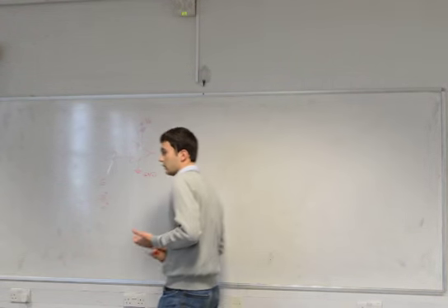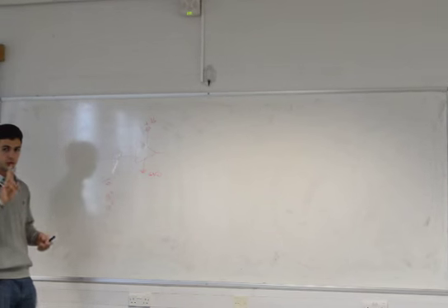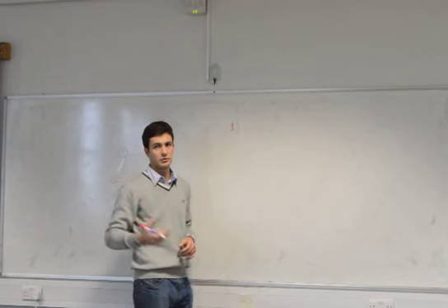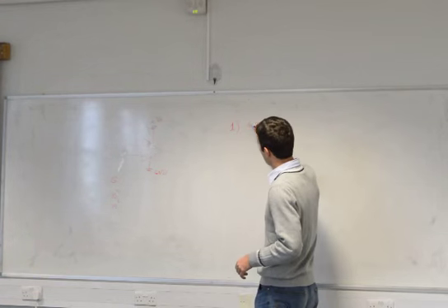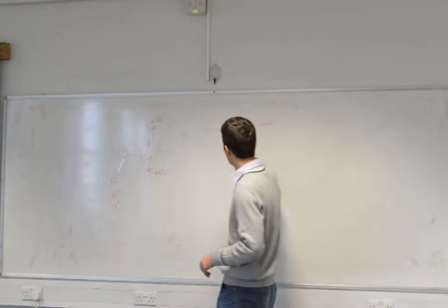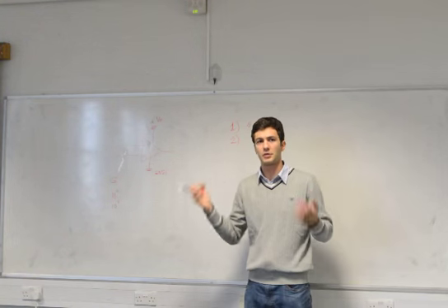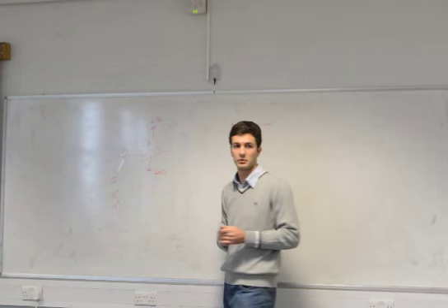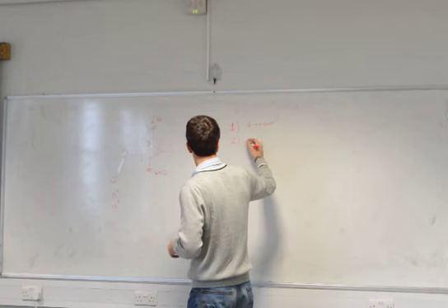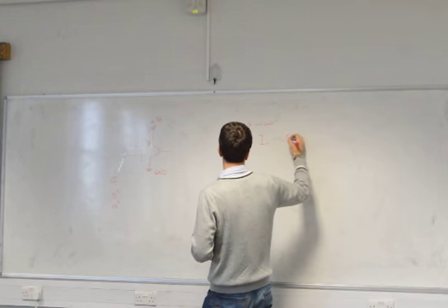There is this idealization of operational amplifier behavior, which says that it has two golden rules. One of them, well, this is formulated differently, so I will say one way, that the gain is infinite. And the second one is that the inputs consume no power. So they have a very high input impedance, yeah? So we will write that I plus and I minus, they are equal to 0.